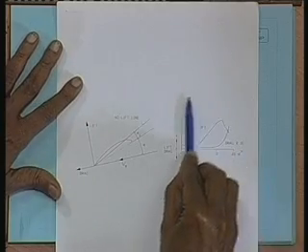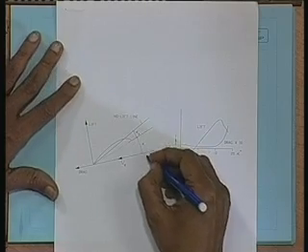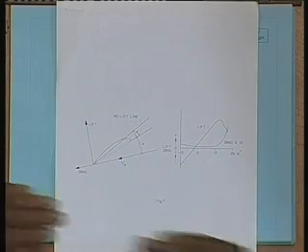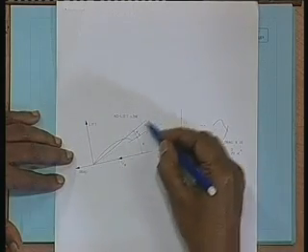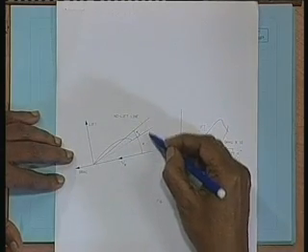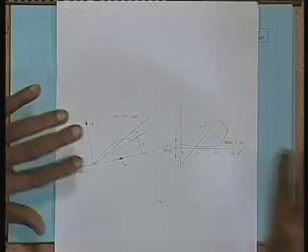So we have to design the propeller so that the angle of attack is within this. Now when you go reducing the angle, when it is at a particular angle to the propeller, there will be no lift. So that angle is called the no lift angle. Only when the angle is created with respect to that, you start getting lift till stall angle. So our aim should be to design the blade sections so that you stay between no lift line and stall angle. Am I clear? Okay, we will stop here and next class we will continue with propeller theories. Thank you.